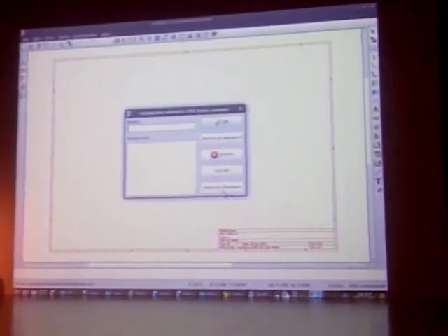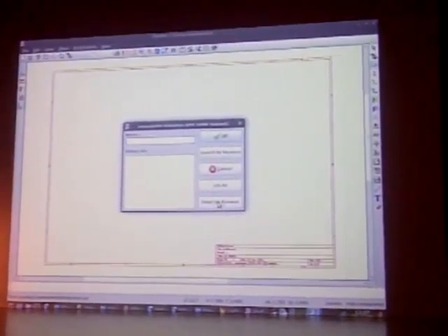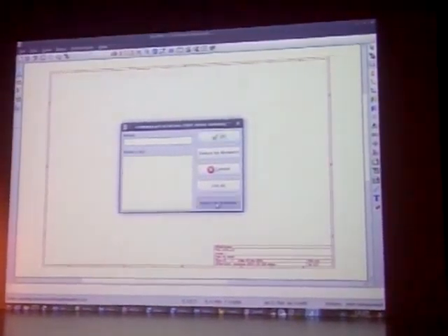You probably don't know the name since you're beginning, so you'll want to select by browser. This brings up a list of libraries. Parts are put into libraries, components. Here are the parts in the ADC DAC. I just happen to know the part I want is in the linear.